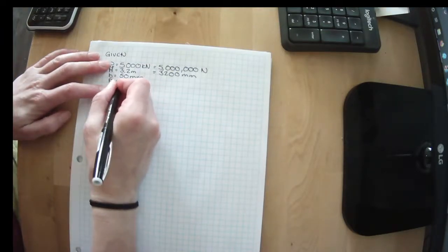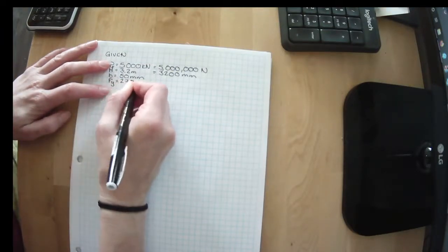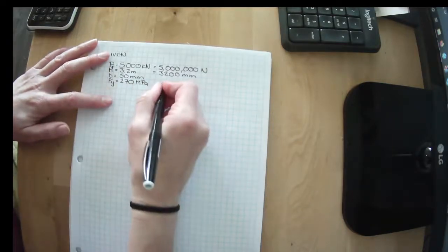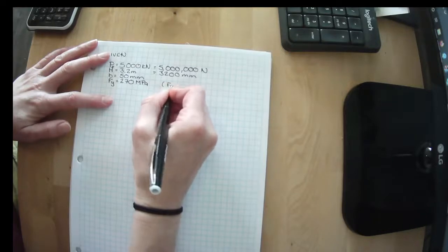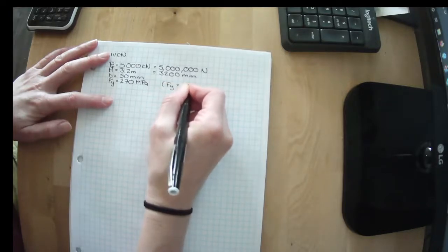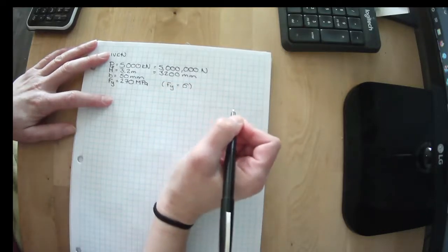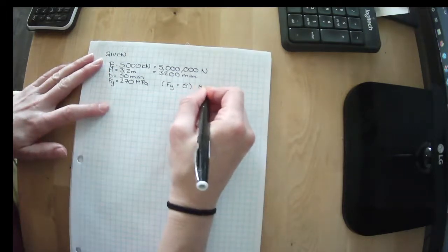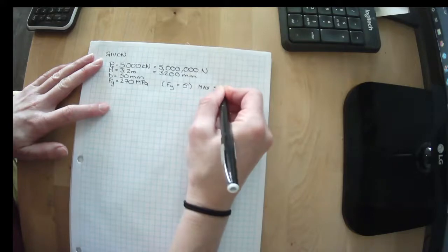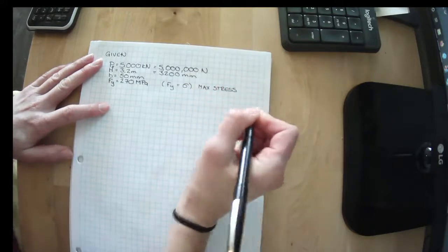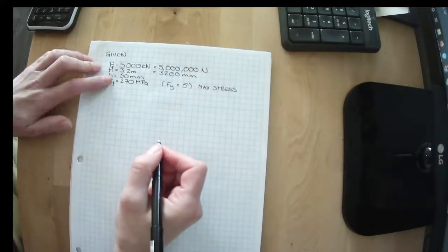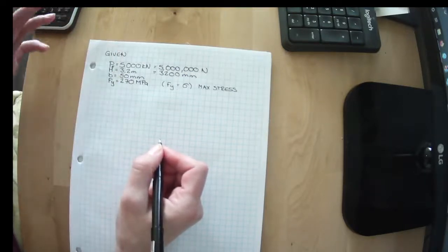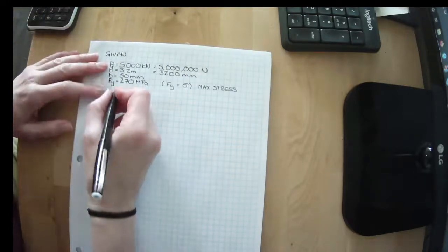So they have given us a reduced capacity of 270 MPa for steel. Fy is another way of writing stress, or in this case, the maximum stress we could see for this. So this is a limit. We don't want to go over that. If we go over that, our object doesn't work.